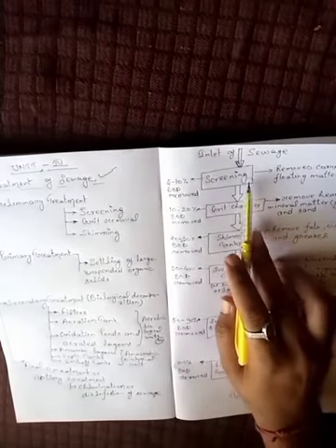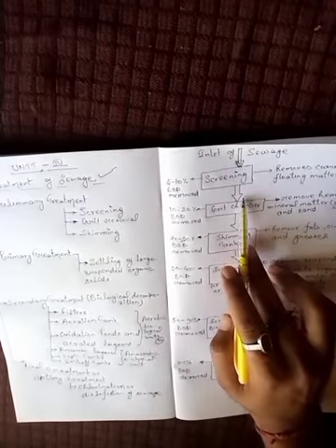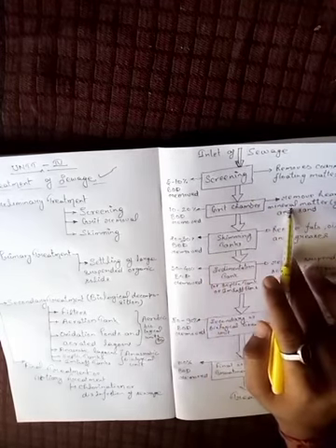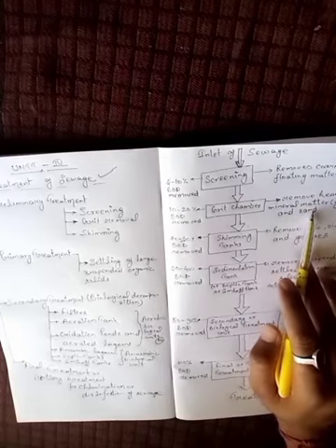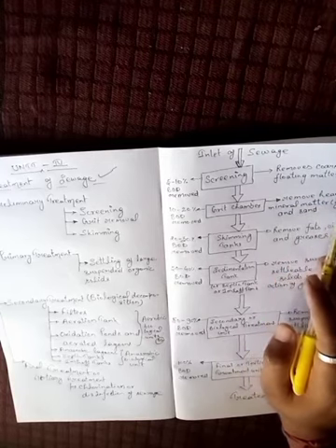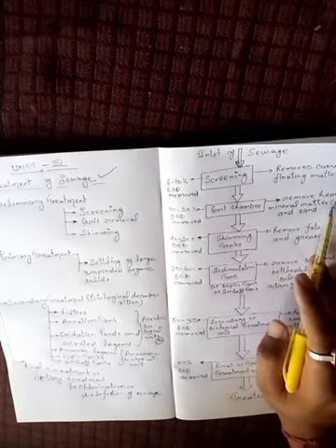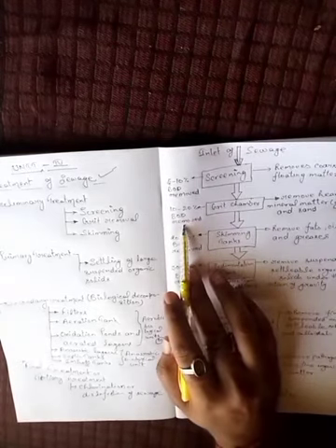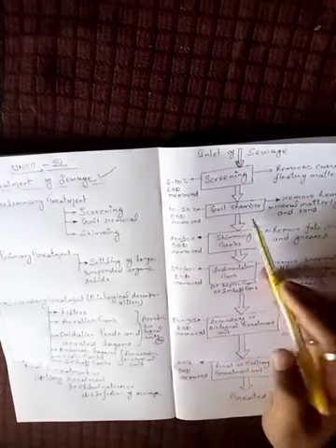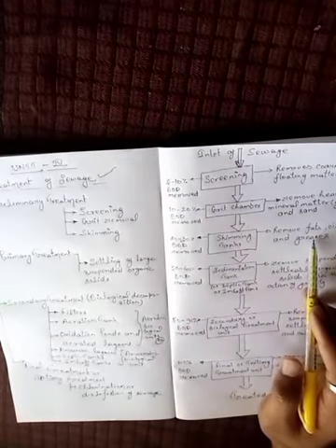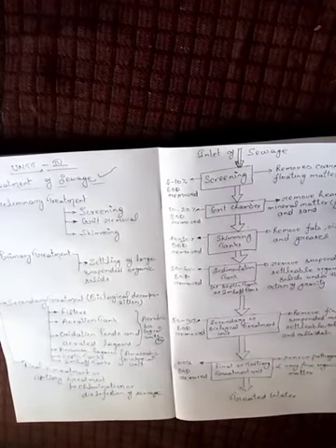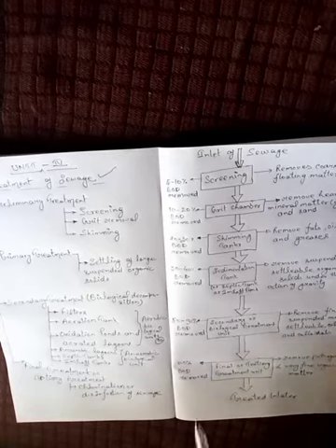Next, the sewage treated through the screens goes to the grit chamber. In this chamber, heavy minerals or matter are removed by the grits or various screen-type structures. In this step, 10 to 20% of BOD is removed by this chamber. After that, skimming tanks. In this step, fats, oils or greases are removed from the surface of the sewage. In this step, 20 to 30% of BOD is removed.